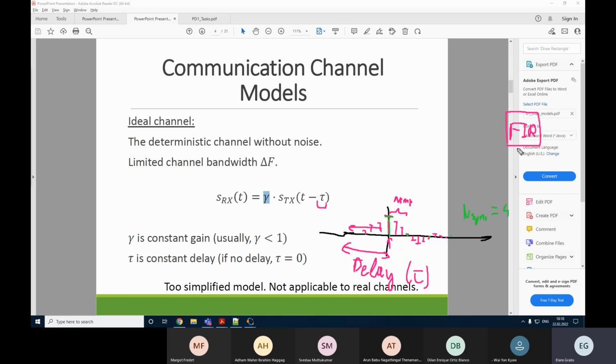So we're going to generate our FIR filter, which has a structure without feedback. We have different delay units, each of which delays our value by one sampling time interval. So it takes the sampling time to transfer the signal by one of these memory cells. This is actually random access memory where we store some values.